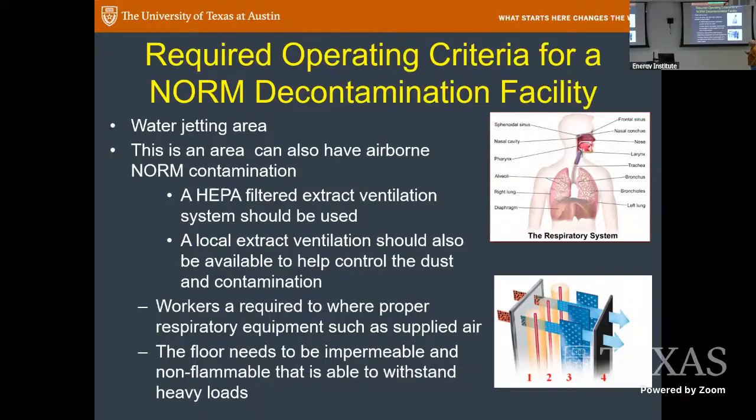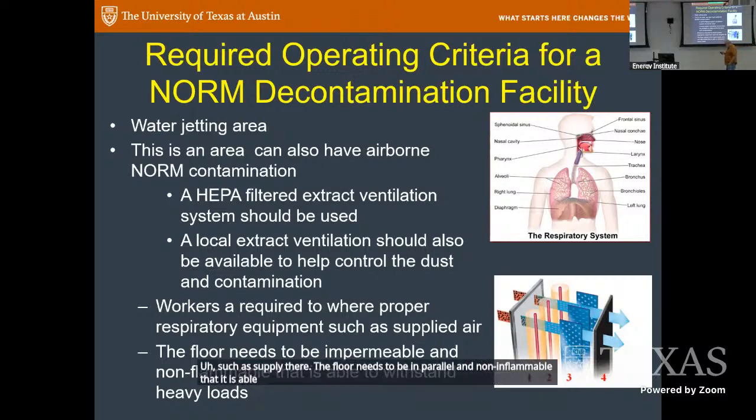So this area, as I said, can have airborne contamination. A HEPA filter extract ventilation system should be used. A local extract ventilation should also be available to help control the dust and contamination. Workers are required to have proper respiratory equipment, which is not inexpensive, such as supplied air. The floor needs to be impermeable and non-inflammable, able to withstand some pretty heavy loads.